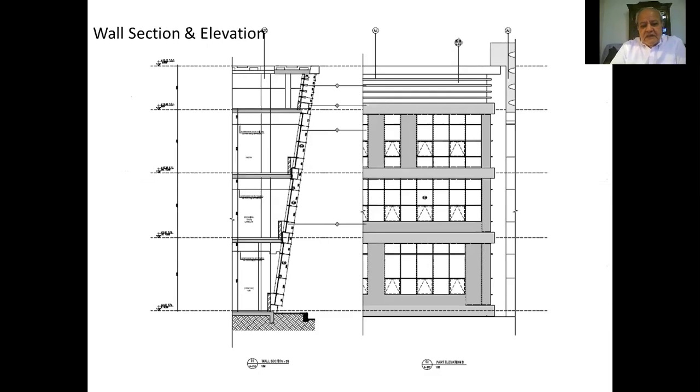This is, as I said, an intermediate stage between the schematic design of sketches, of ideas, of color drawings, models, and then you go to a design development stage. So you look back carefully at the different systems of the building, structural, mechanical, electrical, and see how they will impact the design. Then these drawings will go to the specialist.